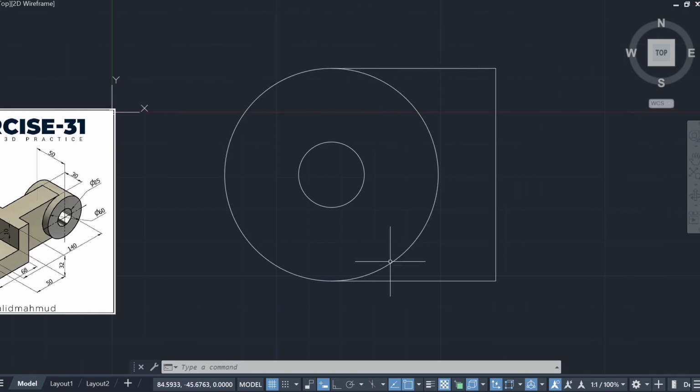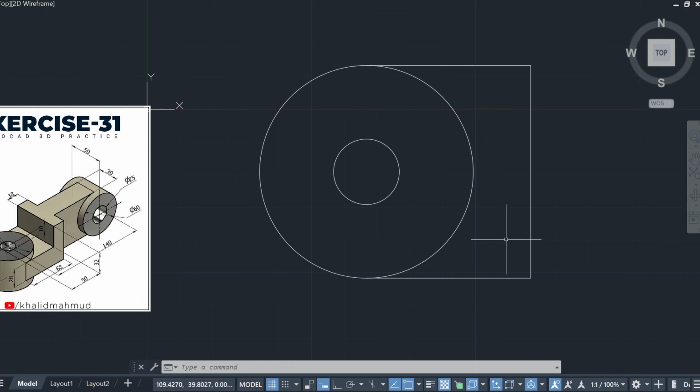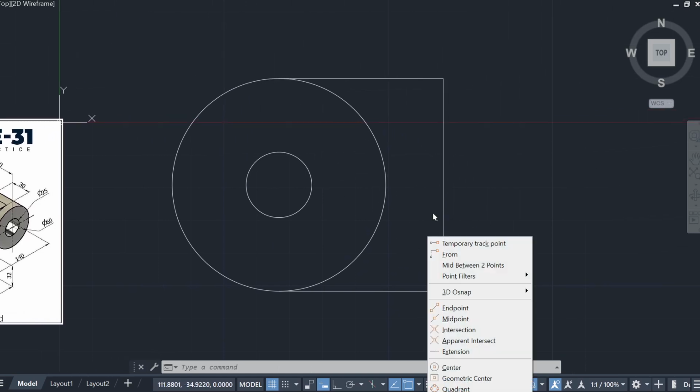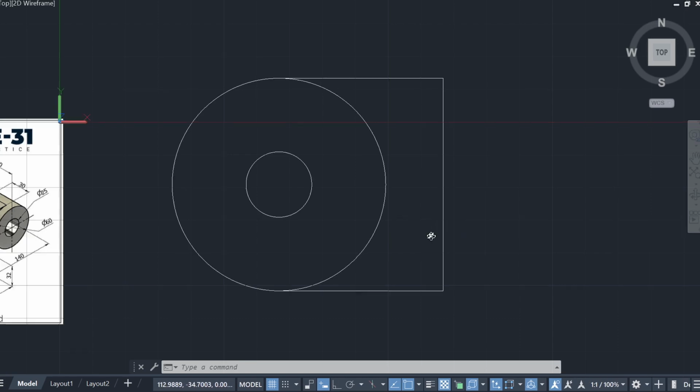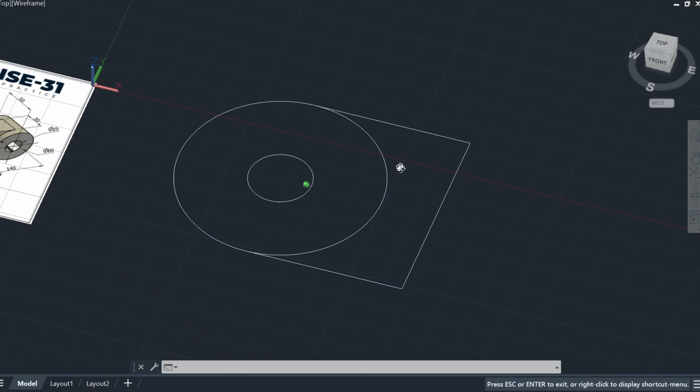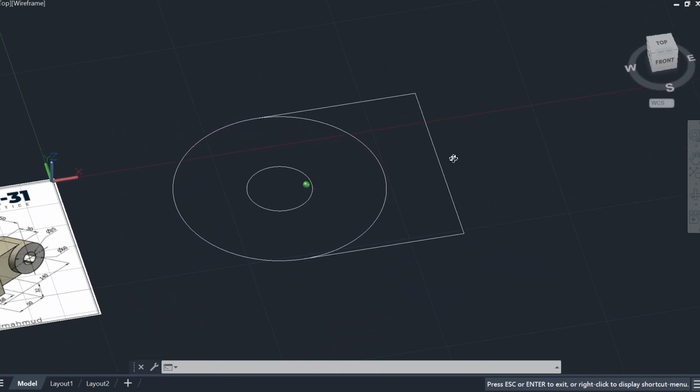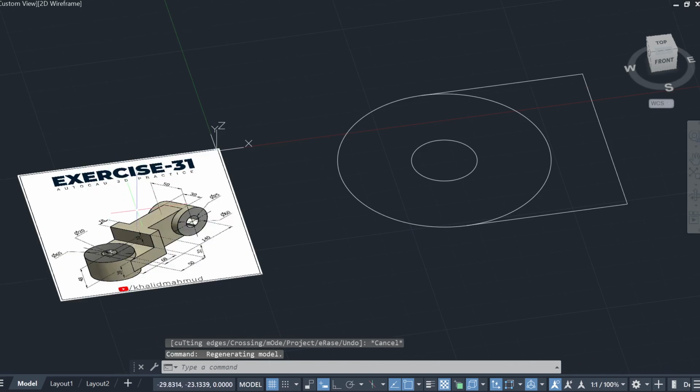Okay? So ang gagawin natin, this is my personal preference, para lang it's easier to look at, I want to rotate my view cube, no? Or I'll rotate my view such that slightly angled siya. So I can do that by pressing shift, tapos pressing the middle mouse button, tapos i-rotate nyo siya. And this is the orbit tool, no? So you can orbit. And notice how your drawing will also be now slightly shifted.